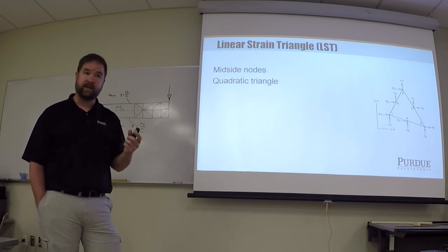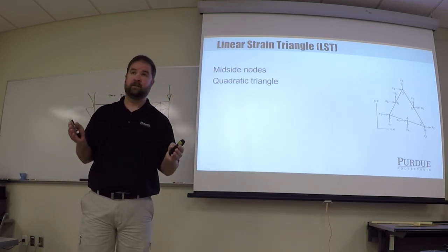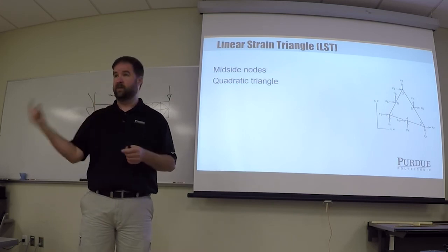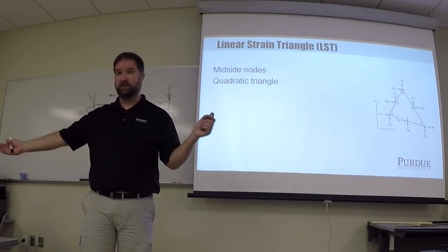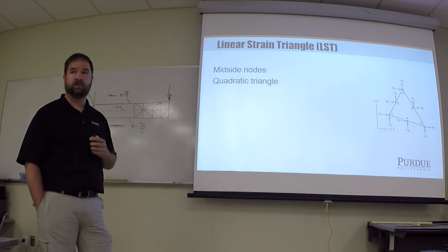And the reason I'm bringing this up, because remember then, that tells you how big your matrices start to get. So one element's a 6 by 6. Multiply that by the number of elements in the structure, and that gives you the size of the matrix you have to solve in order to do the calculations.